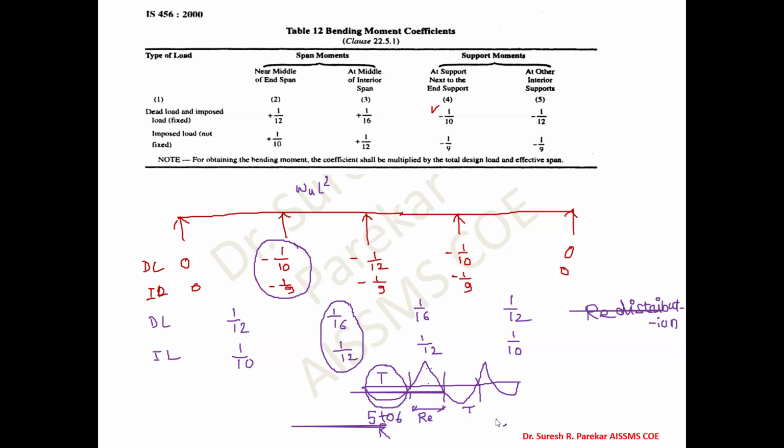Now you have to go through the curve that we have drawn in the class. We have 3 curves. First curve we have, that is actual bending moment diagram. Then we are going to reduce this bending moment diagram by the value that is of support. Suppose we have support 100, and if we have redistribution is given 20%, then we are going to reduce all the values, or we are going to draw a parallel curve reducing all values by 20.